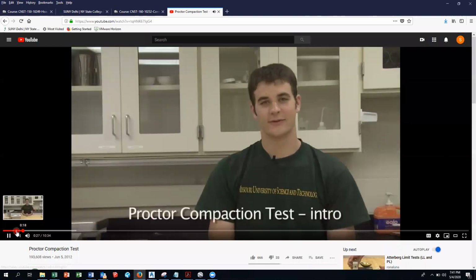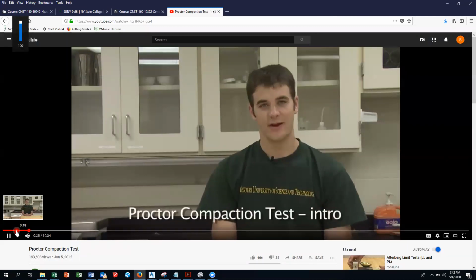Resume recording. With the Missouri S&T Geotechnical Labs, today we will be going over the laboratory procedures used for a standard Proctor compaction test. This short video will demonstrate how to conduct a standard Proctor compaction test in accordance with ASTM specifications. This test was developed to evaluate the level of compaction of field compacted soils. The soil is compacted into a mold at a specific energy comparable to the energy used in the field.